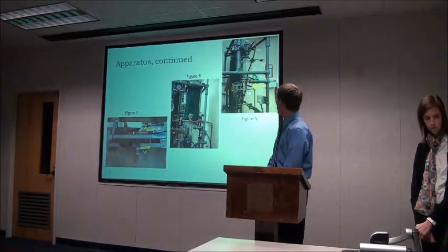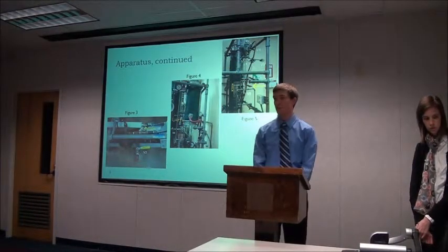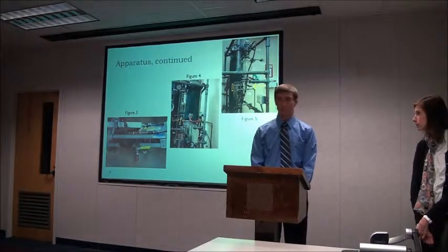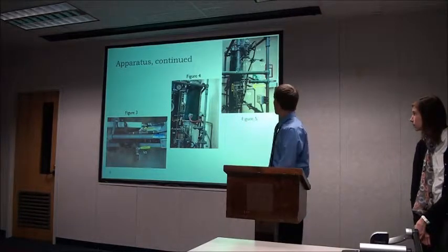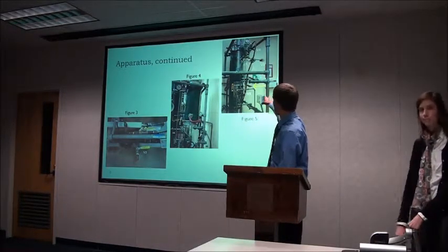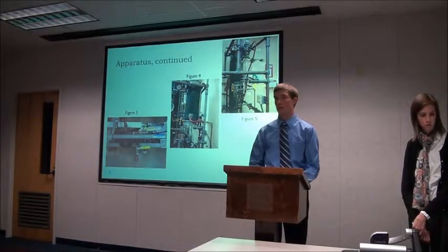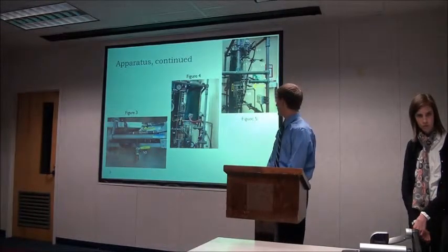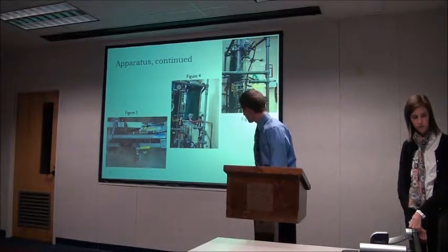where we would open valve 5 in order to let the liquid from the evaporator come out and see what we have for the liquid flow rate. For the pressure, in order to change the pressure for the second week, what we did was we closed the valve, which is where the yellow arrow is in figure 5. That way we would have a different evaporator pressure in the vessel itself. And we'd also close the other valves to the system.